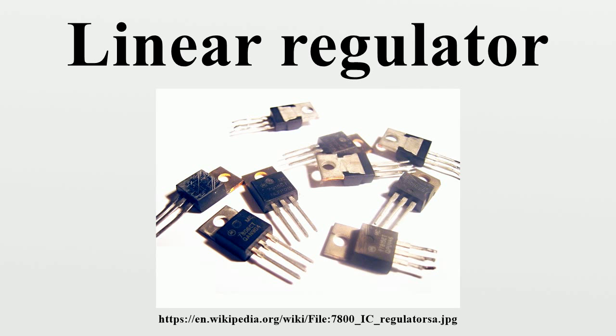a linear regulator may be preferred for light loads or where the desired output voltage approaches the source voltage. In these cases, the linear regulator may dissipate less power than a switcher. The linear regulator also has the advantage of not requiring magnetic devices, which can be relatively expensive or bulky, being often of simpler design, and being quieter. Some designs of linear regulators use only transistors, diodes and resistors, which are easier to fabricate into an integrated circuit, further reducing their weight, footprint on a PCB, and price.